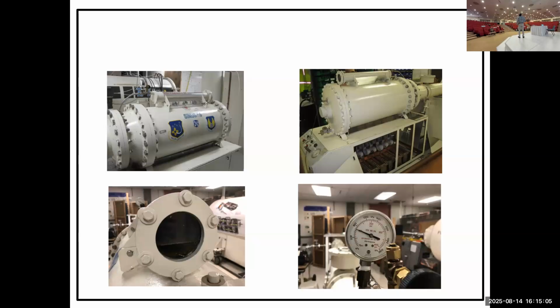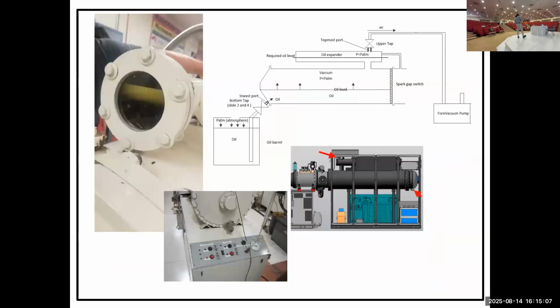So we had to vacuum this tank and have this inlet suck the oil in. But when we do this, we start boiling the oil. You see, because with negative pressure, reducing the pressure, the boiling temperature drops. So that was a very, very crazy task.